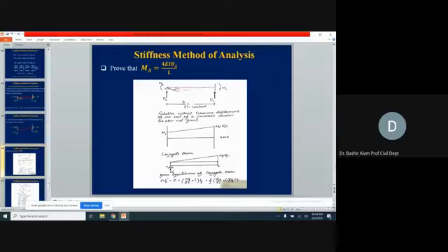Now, if we want to draw the bending moment diagram, here you see the bending moment diagram. We don't have any shear values, no loading within this span now. Shear here is RA, shear value here is RB. So if you want to draw the bending moment diagram in terms of this MA and RA, what will be the bending moment here? At A, we have MA.